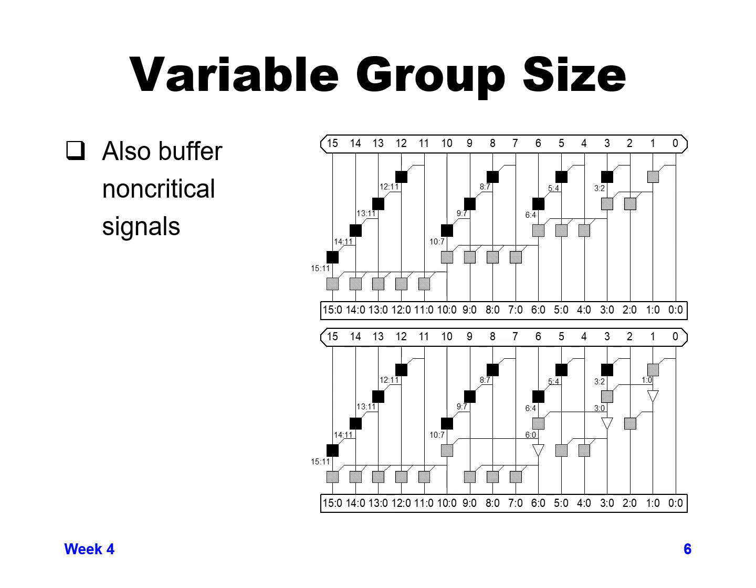That's going to slow down the output from bit 3 because it has more capacitance to drive. So what we can do is add a buffer at the output of bit 3, where the output of the buffer drives bits 4 and 5, and the output before the buffer drives solely bit 6, because our critical path is to the higher order bits. So driving a buffer plus bit 6 is less capacitance than driving bits 4, 5, and 6 together.